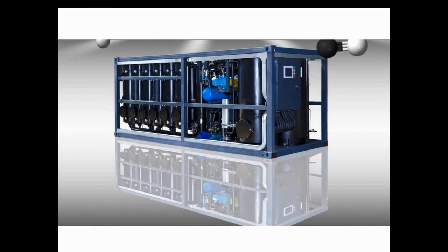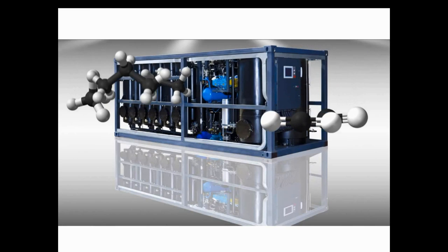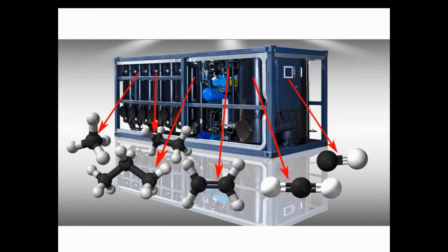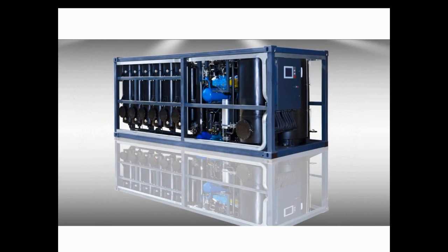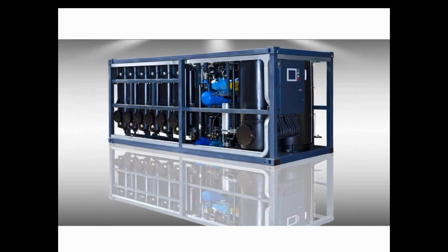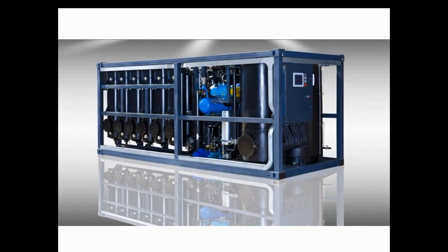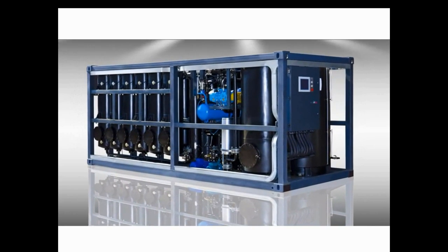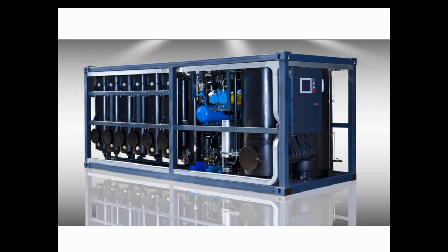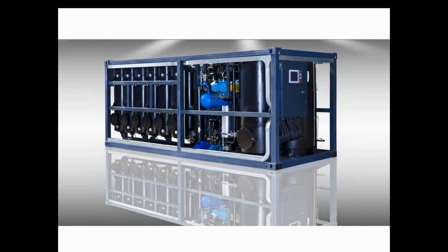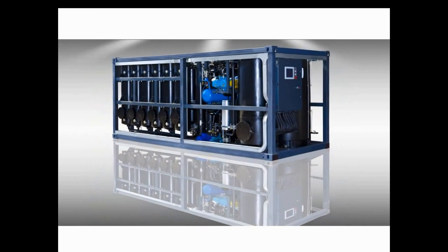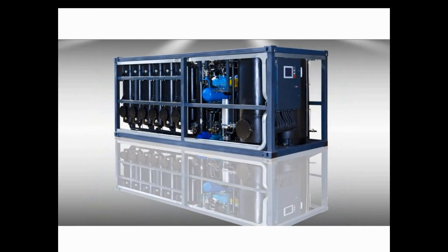Regular purification is an important part of transformer maintenance in terms of regeneration, as it reduces oxygen, which is a driver of oil oxidization. As well, purification removes combustible gases such as ethane, ethylene, methane, carbon monoxide, and carbon dioxide. All of them are in the oil, and as a transformer is aging, they contribute to oil oxidization.